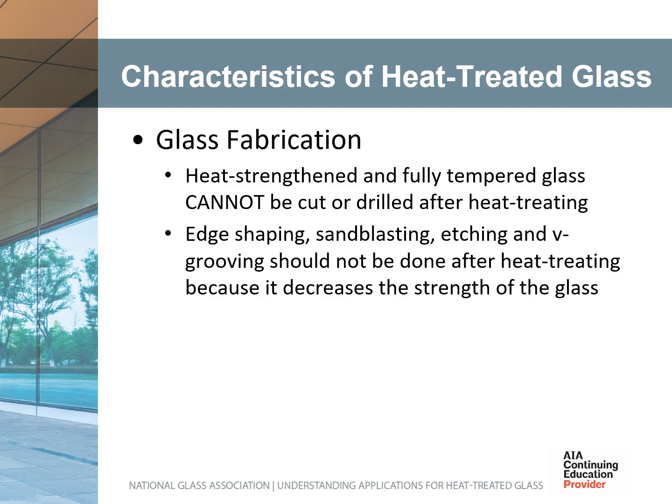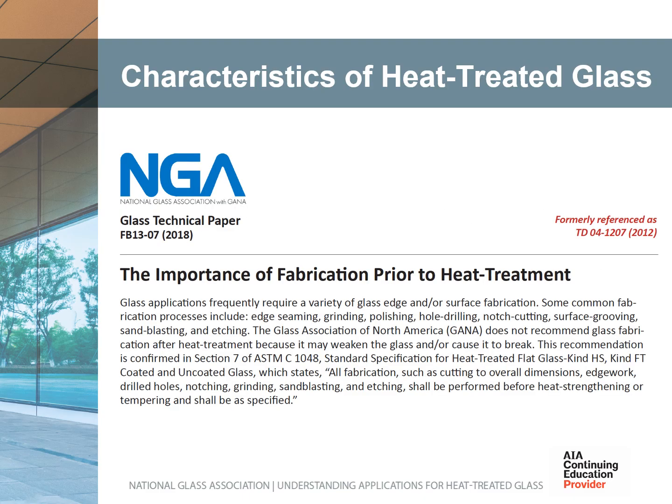Because heat-treated glass has significant internal stresses, post-fabrication procedures can result in breakage or weakening of the glass. For instance, heat-treated glass cannot be cut or drilled post-treatment. Edging and etching also impact the strength of glass. See NGA's Glass Informational Bulletin, The Importance of Fabrication Prior to Heat Treatment for details.